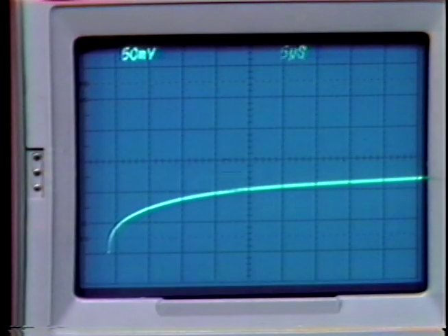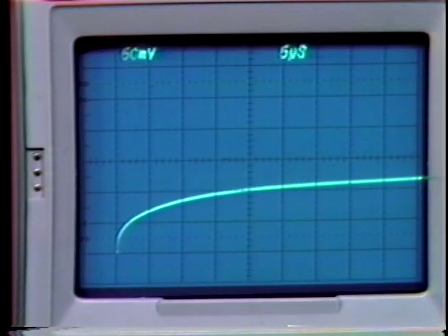We spoke a little bit about this prolonged settling transient that results when we have a pole zero doublet. We looked at that in conjunction with the 1 over S squared compensation last time. I mentioned the same kind of thing happens with a lag network. Well, here we have an extreme example of this kind of thing.